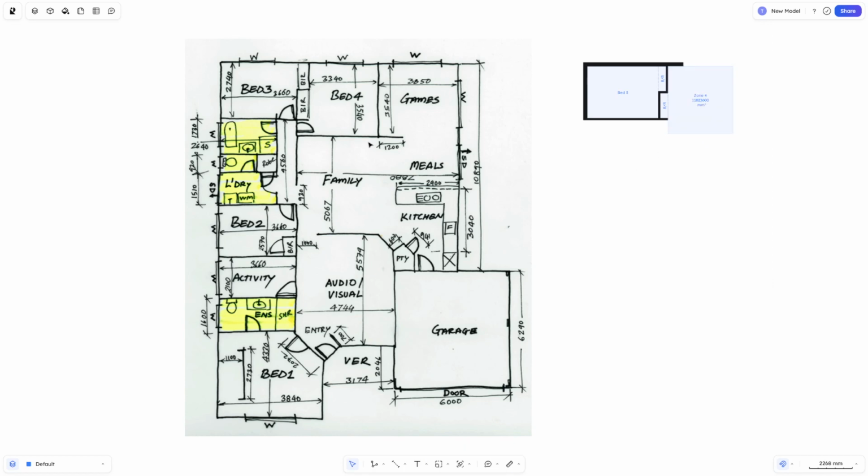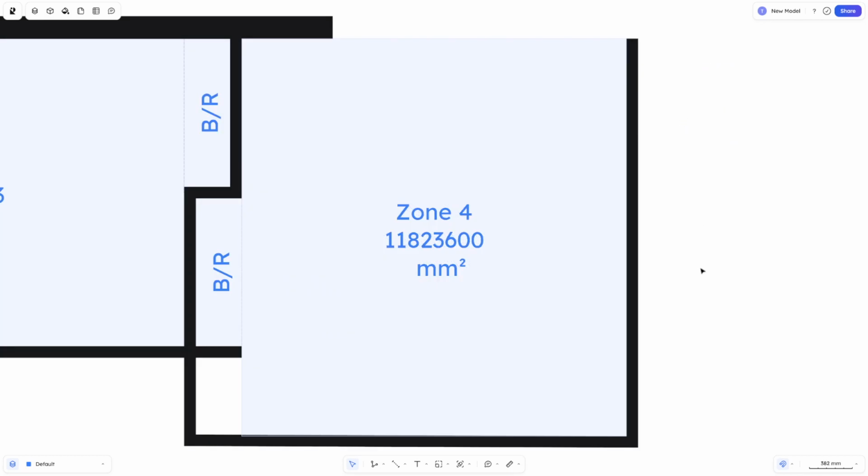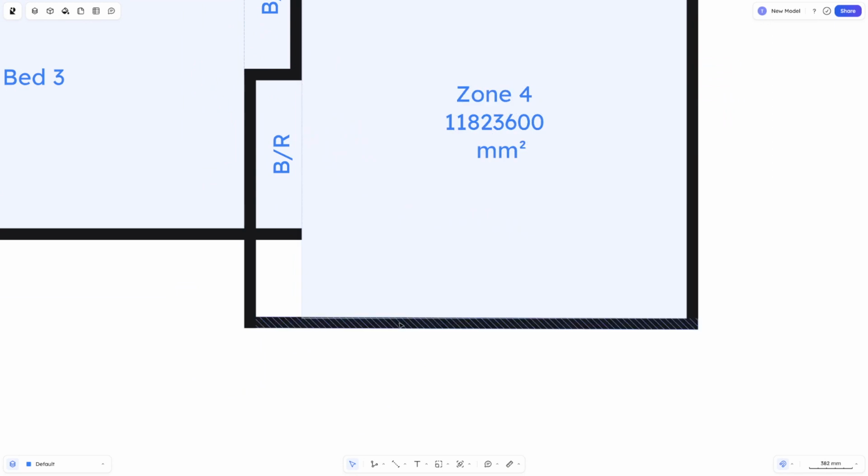Now, one thing that's slightly different about this room is this bit of wall here actually needs to go over to here. So what we are going to do is drop this wall down, and we will fix it into here. So this is this bit here, so we've just drawn this crossing. So the way the door's going to sit in, it's going to sit against this room to enter into the room. So what we can now do is quickly zoom around the edges here, bring those walls to the outside, F into there to zoom in again, and it's slightly off.